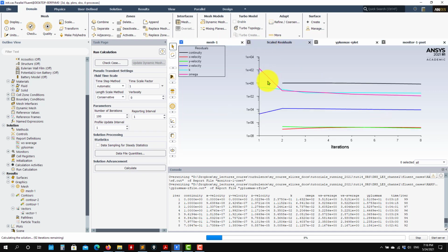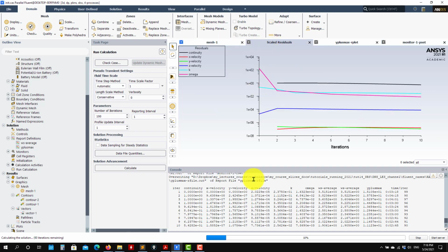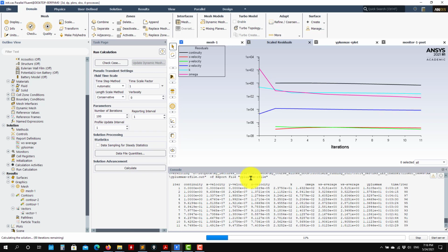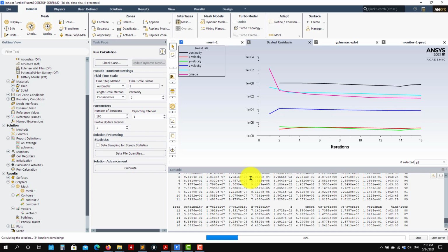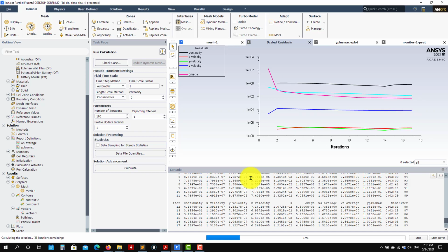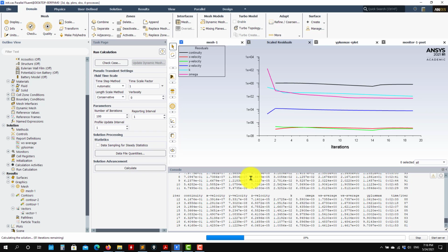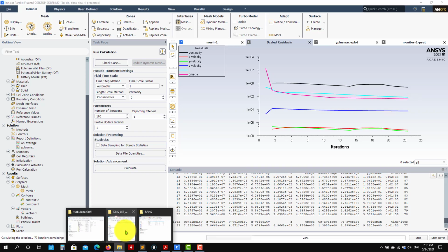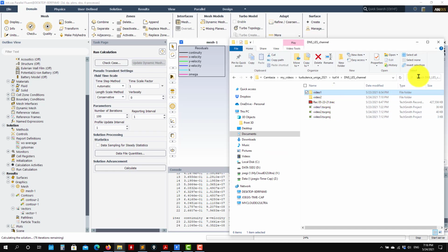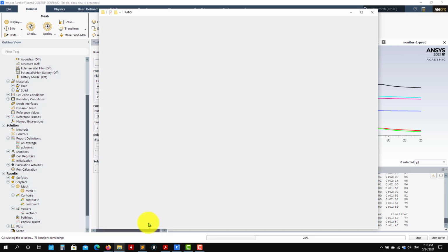This is the RANS. The idea with this workflow is that first you start with the RANS. You compute integral length scales and refine your mesh according to the physics that you're getting. You also get some insight about the physics of what you're doing. Then you move to URANS using the previous solution. Just to refresh your memory about that.